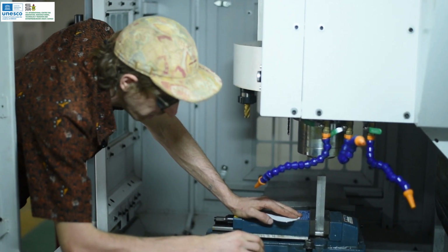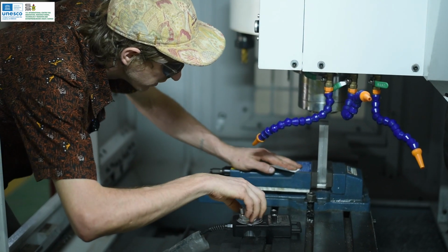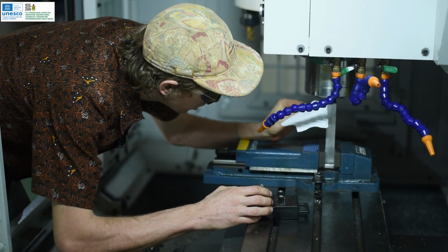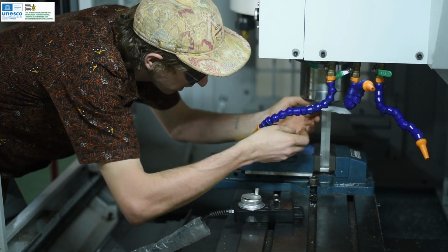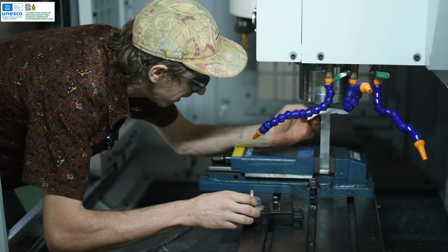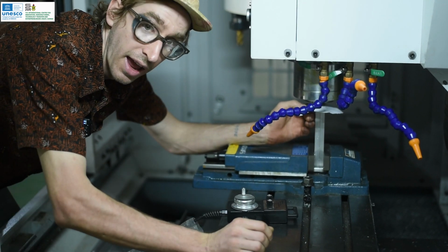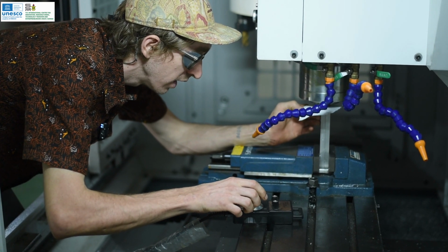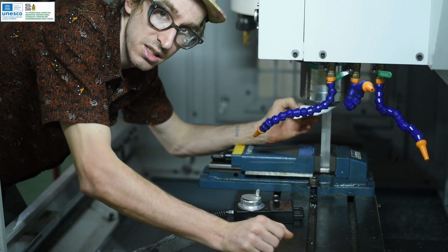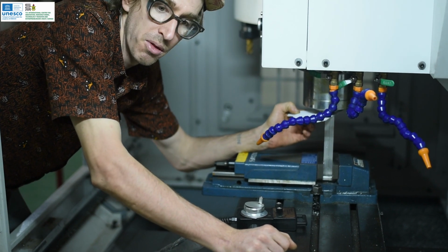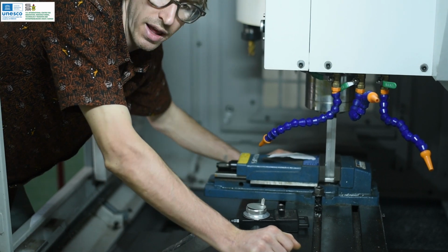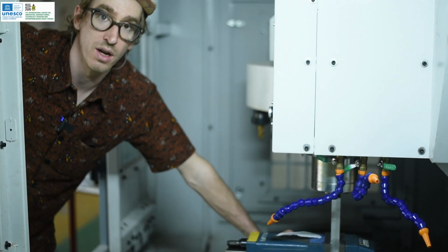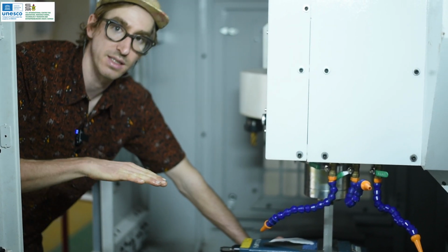we're going to move that spindle head down until it's very close to the workpiece we're using to set our tools. You could use a 1, 2, 3 block in this case. You could use any piece of square stock, something that is flattened nicely. And you're going to get close to it, add a piece of paper, go down to smaller increments, and then just jog down until that spindle face clamps on a piece of paper without ripping it. You want to be able to pull that out, but you don't want to add a whole lot of force onto your spindle. At that point, we're going to come back to our controller and set our spindle face as T10.